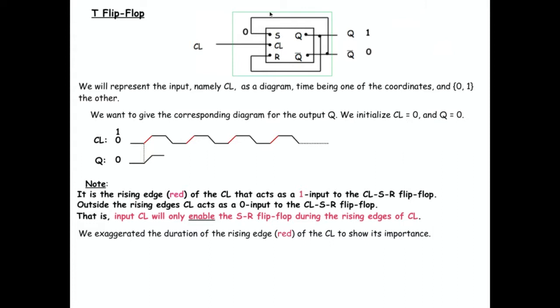And when clock is 1 again, then, well, the 0 will remain 0, but when S is 0, R is 1, and that will be ANDed with the clock, and then it will go into the flip-flop gate, and it will reset it, right? It will reset Q back to 0. So Q is going to continue to be 1 up until here, where it will get reset to 0. Yep, there Q got reset to 0.